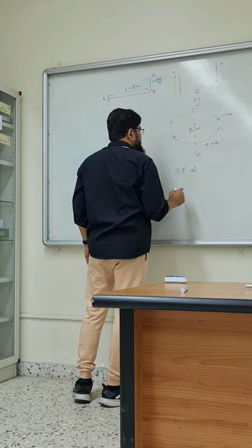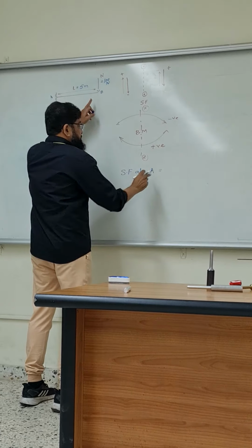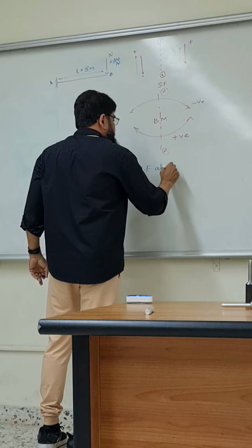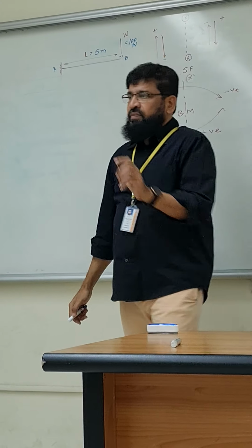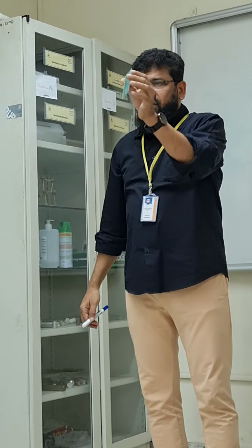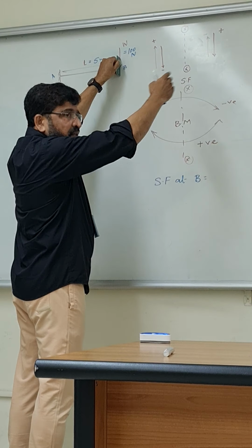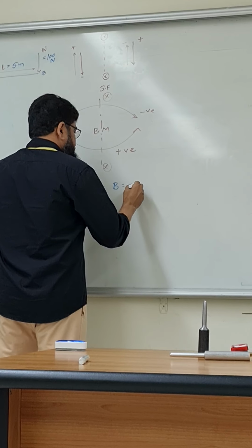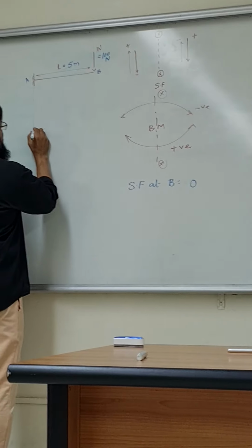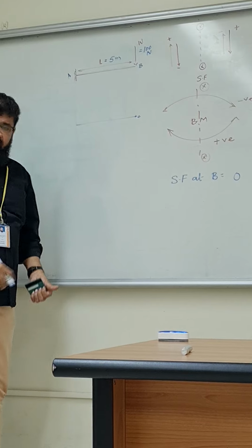Now what is the shear force? Shear force at A. Sorry, shear force at B. Do you have anything on the right side? No. There is nothing, is it? So it is equal to 0. So I have 0 here.